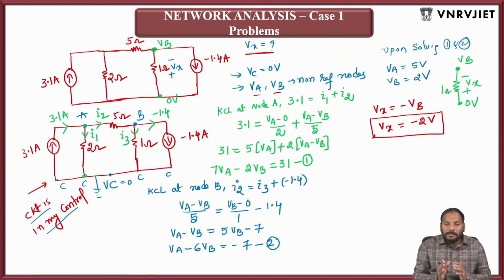Okay, so the important thing what I have done, dear students, is I have erased the value of Vx before starting the nodal analysis. And I have taken the circuit in my control. Then I have solved for nodal voltages VA and VB. Then once again I finally go back to the original question, what is being asked, that is the calculation of Vx. And then Vx you can easily calculate using nodal voltages.